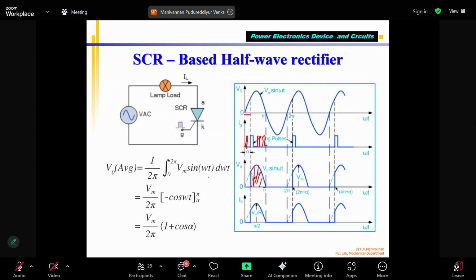So take down this formula for conduction. You can say V average, correct? The load voltage will be varying by varying the conduction angle, where I give my gate pulse with respect to 0 to 180 degrees. Within 180 degrees, I can give my gate pulse anywhere. So accordingly, the current flowing through varies. So take down the formula. This is the final formula.